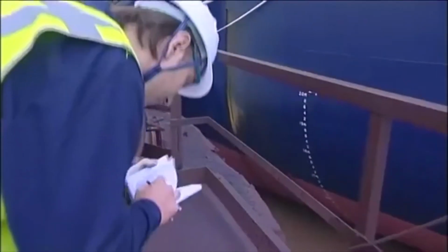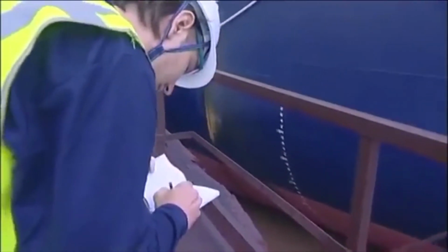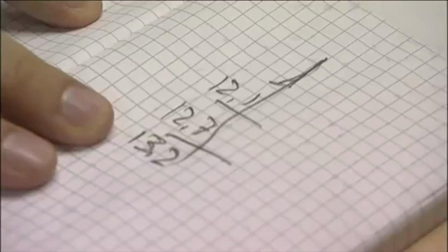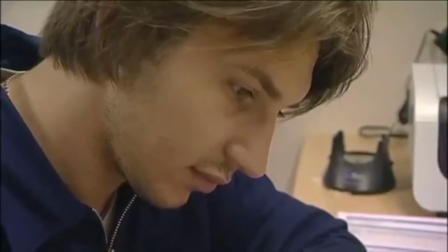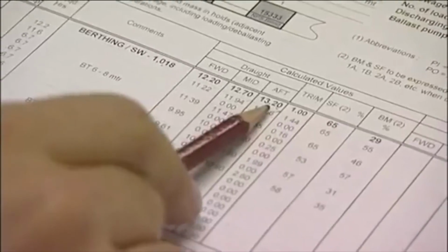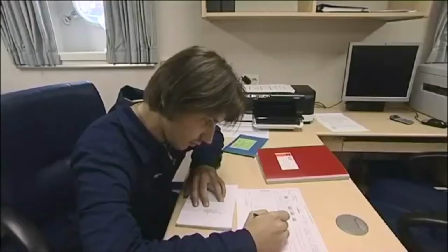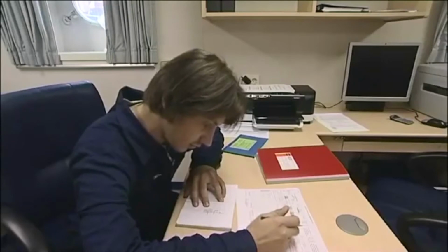Ship's personnel must carry out draft surveys at regular intervals to check the calculated ship's loading condition, the cargo weight, and its distribution. The recorded readings should be checked against the loading plan. This information, together with loading rates, ballast synchronization, stress and displacement calculations, all help to balance the forces acting on the hull.